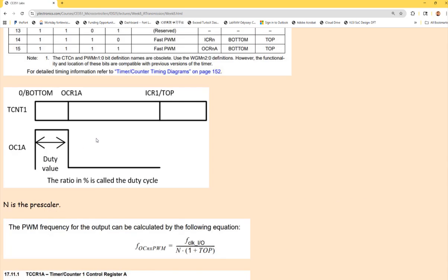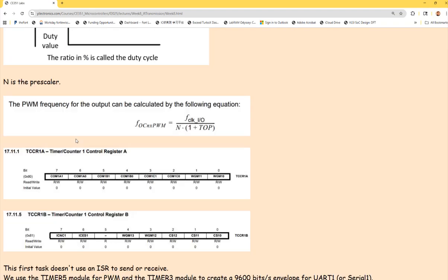If you search on Google, you are probably getting answers regarding how to turn off the PWM or just output a 0. It tells you that, hey, you can directly just write a 0 to this value because this value determines the on time. Right? Actually, it didn't work. Spent a lot of time on it. It didn't work at all. But there are certain ways to turn it off, which works really well.